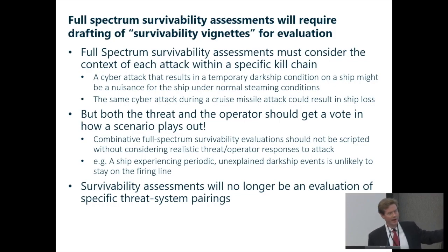So, and the last bullet is important. In the past, we've had sort of the luxury, I'm going to say, whenever I've presented results from, say, a survivability assessment, we always end up with a probability of kill given hit at the end of the day. Against this threat, you have a PK of 90%, right? We have to get away from that kind of thinking because, number one, it was never as specific as we tried, with as many decimal places as we always tried to put behind it. But also in the concept of full spectrum survivability operations, that number really doesn't have any value on its own.